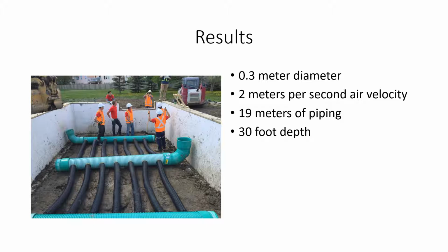The way we have this set up now, it would keep the air temperature in the greenhouse equal to the air temperature at 30 feet and the mean annual ambient air temperature at Rexburg. We could also dig a little shallower and just keep the greenhouse above freezing, and that way plants could live year-round even if they wouldn't be germinating year-round.